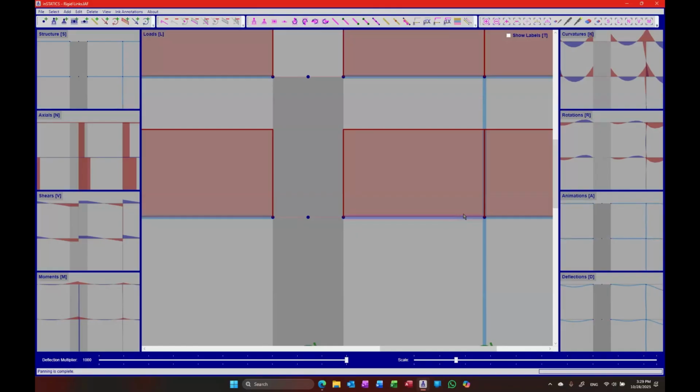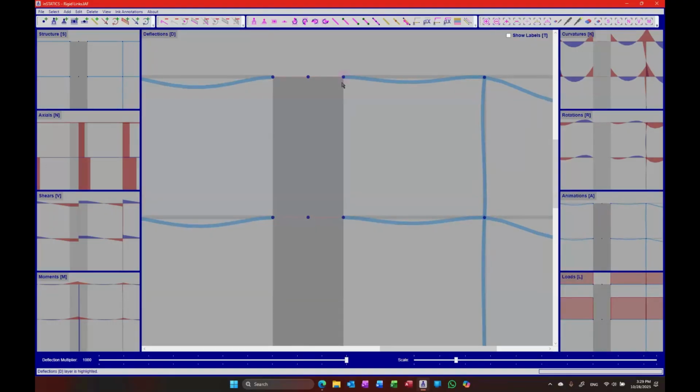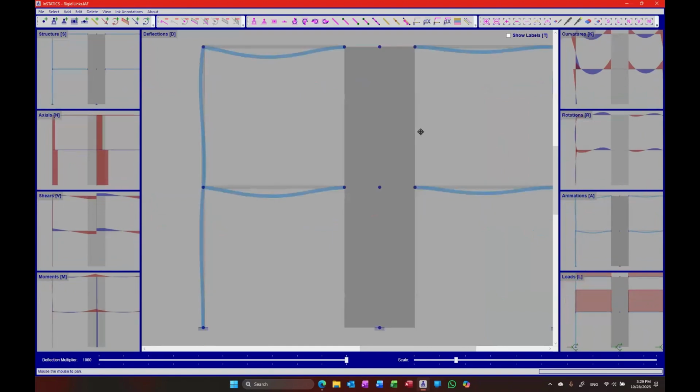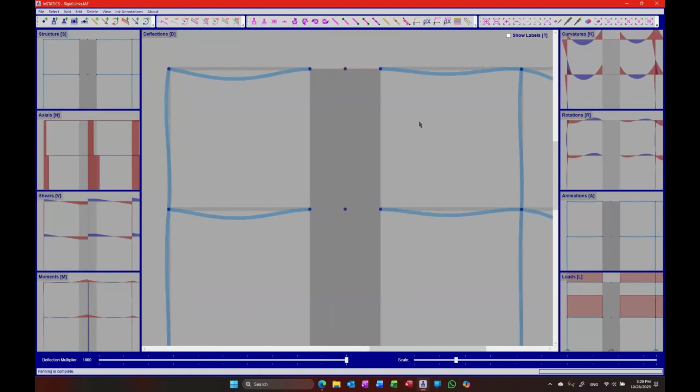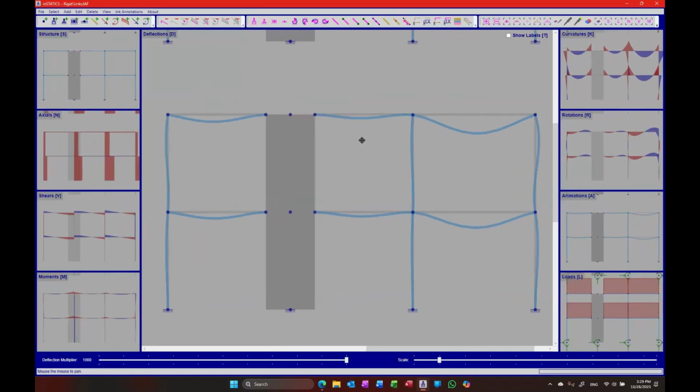Even if it is dead load, if you have some sort of floor covering or something like that, it's not going to go into the wall. It's going to end right here. So we simulate the behavior correctly. And if you look at the deformed shape, now you can see that the deformed shape is also very different, right? I don't see the deformation starting inside the wall, but at the face of the wall, like it would really do in real life. So we make use of these rigid links to simulate a closer to real behavior.